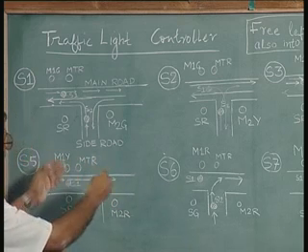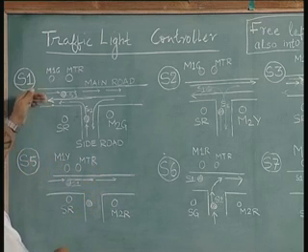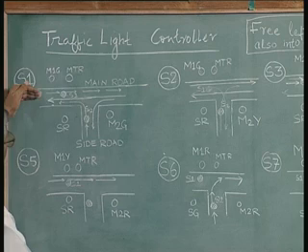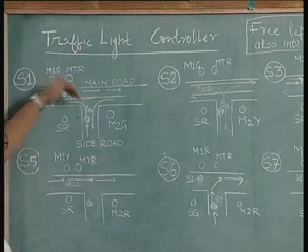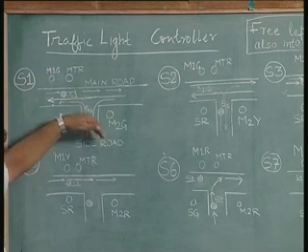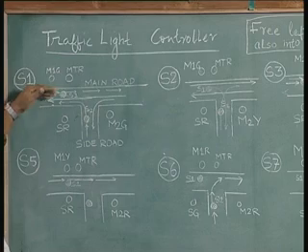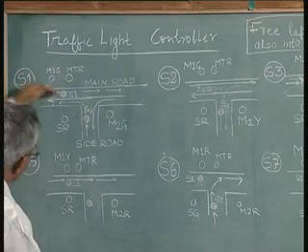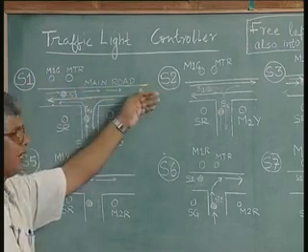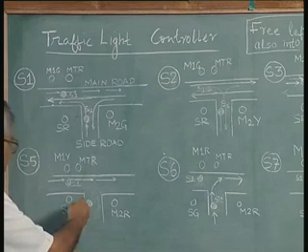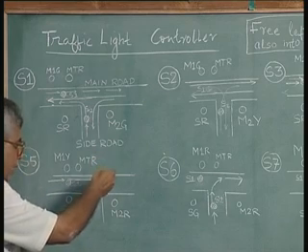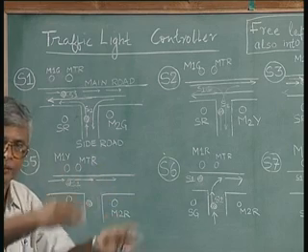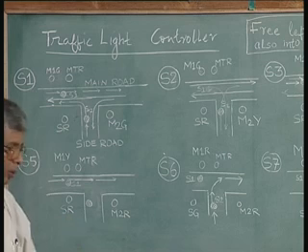For the turn from the main road to the side road, the right turn, we will allow the main road traffic in one direction and only stop in this direction. Whereas for turning from the side road to the main road, we will stop traffic in both directions. This is one of the specifications you have to be careful about, remember this.